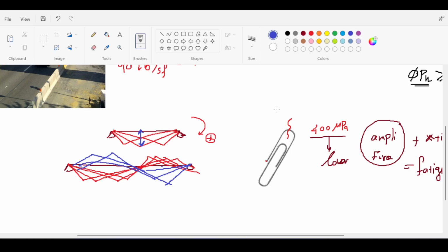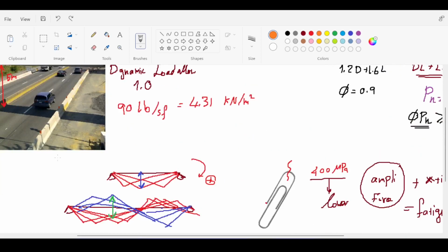So when you have a continuous bridge, the amplitude of motion is much larger than in a simply supported bridge. That's what I tried to say when I was talking about fatigue. Now, the amplitude check, we understood. What about the force? Luckily for us, to be honest, in pedestrian bridges we don't really care about fatigue too much.